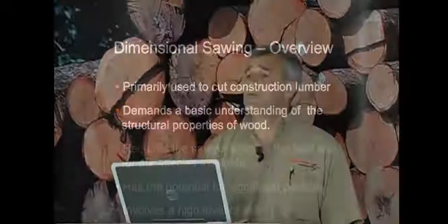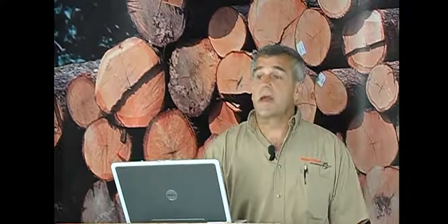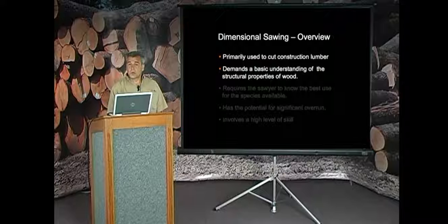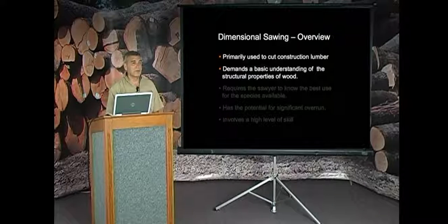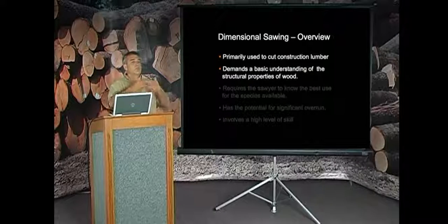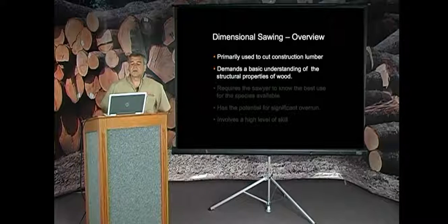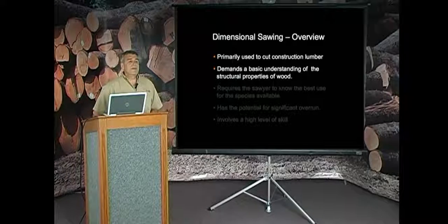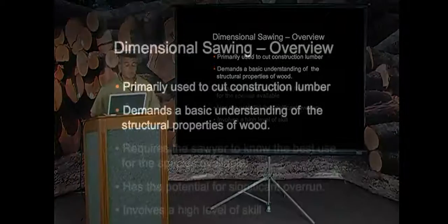If you're going to be producing lumber that your customers or you are counting on to hold the roof up over their head, I think you need to understand some of the structural properties of wood and how wood acts under load, how it acts when you point load it and you're asking it to hold a floor or a ceiling up, but you're going to put a piano up on that second floor. So we need to have a basic understanding of the structural properties of wood.